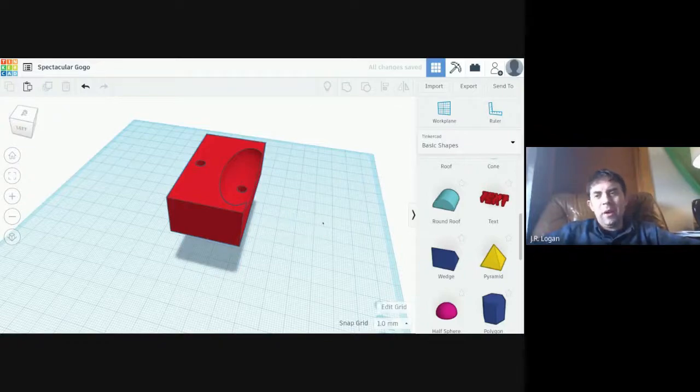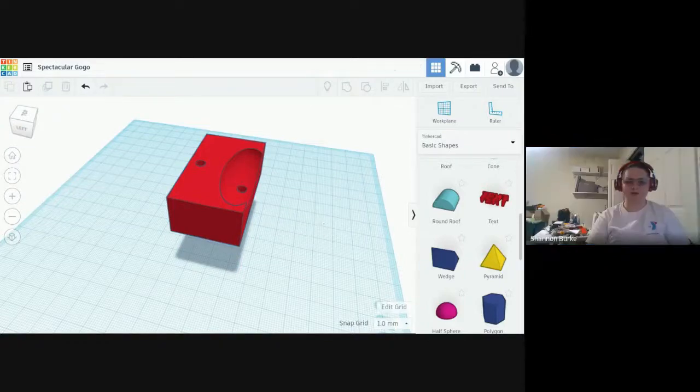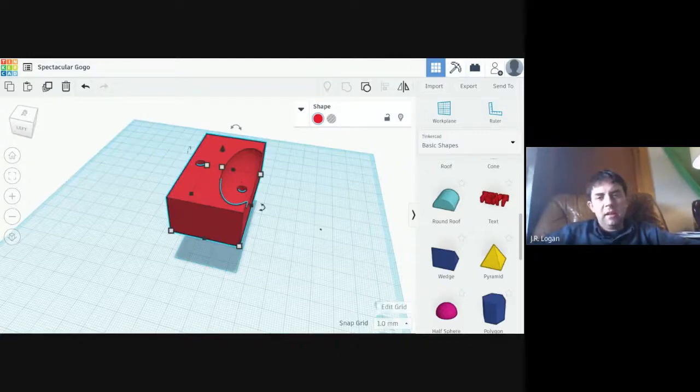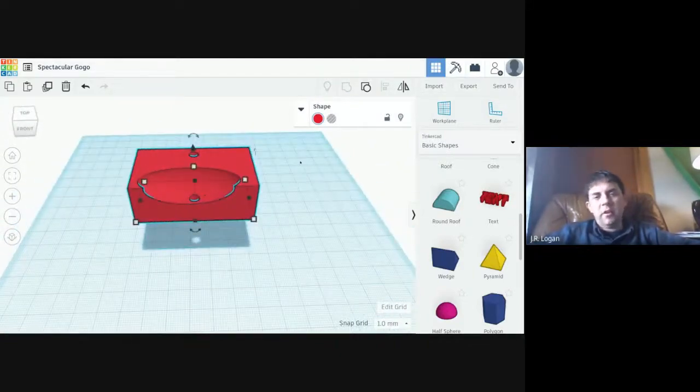Might just take a little practice. Yeah, I think I might just be grabbing in the wrong places because it keeps wanting to draw a little red box. So try holding down Shift and just clicking. Sometimes the drag, you could select other objects by mistake and so on. So it's good to get used to the Shift.